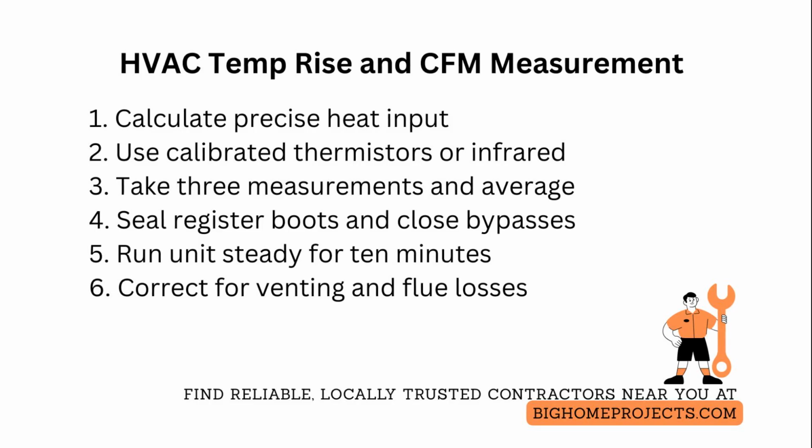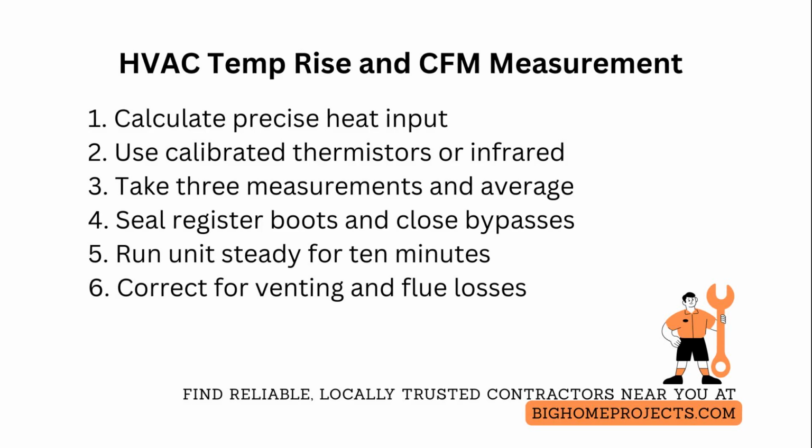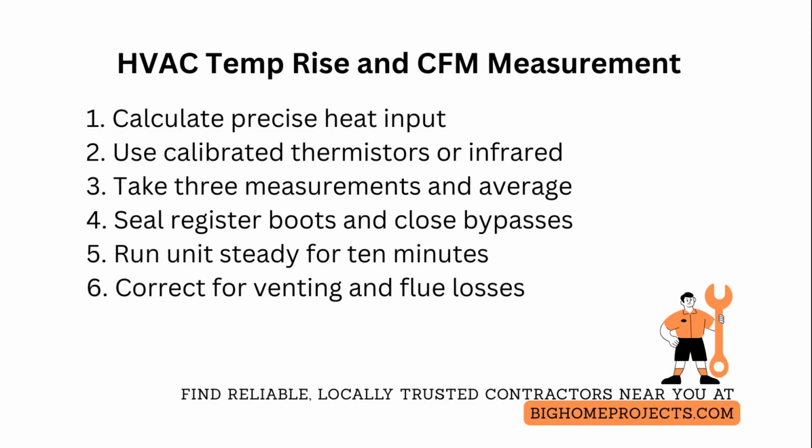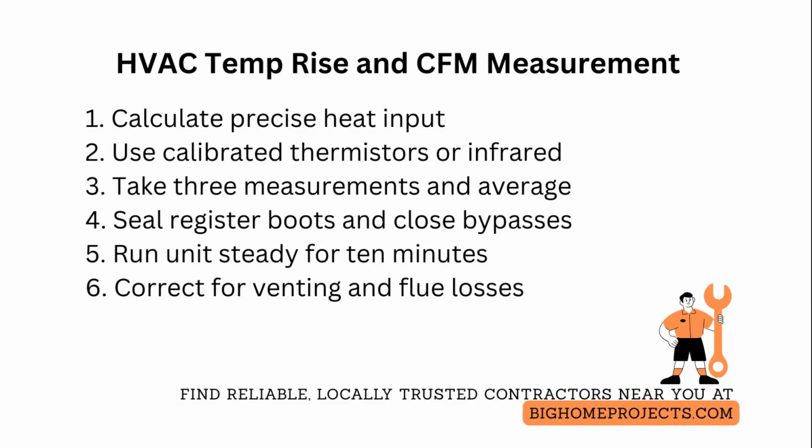Document ambient conditions, altitude and indoor versus outdoor temperature, and static pressure. Because air density affects CFM, apply a density correction factor when above sea level. If the calculated CFM is outside the expected range, repeat the measurements and inspect for dirty filters, duct restrictions, or collapsed flex runs, which are common hidden causes of low airflow.